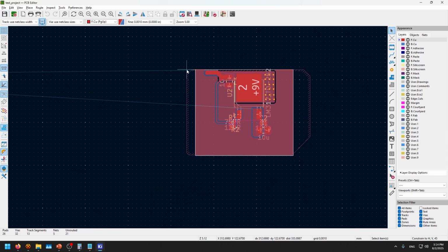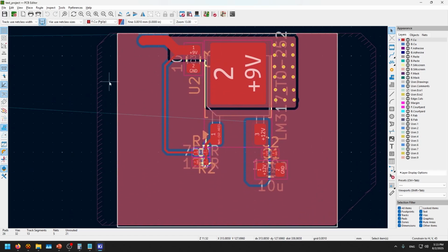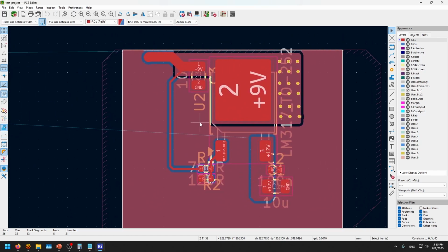And of course, if your load is something very far, it is always recommended to take it just before you get to your load, so that it compensates for the inductance and the dropout voltage that can or cannot happen during the layout.